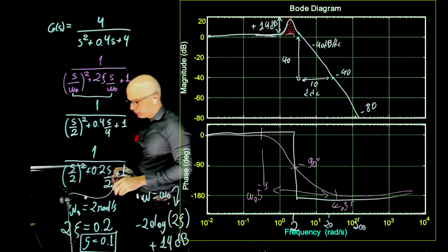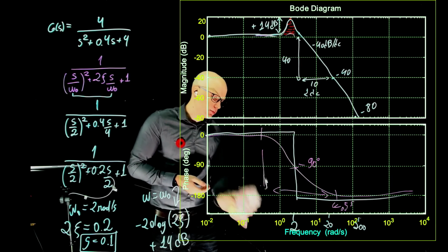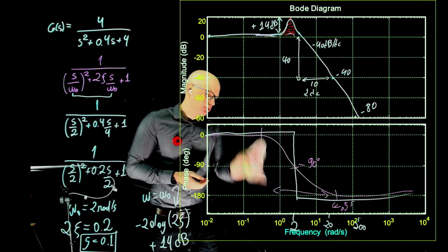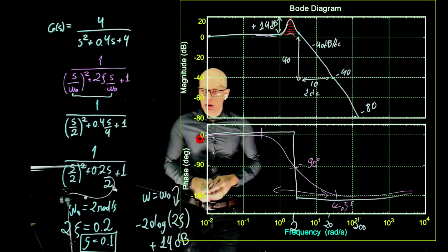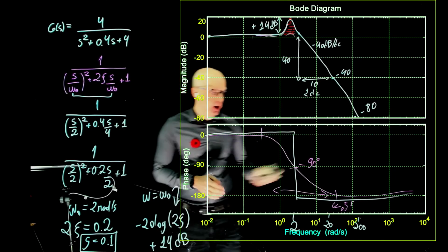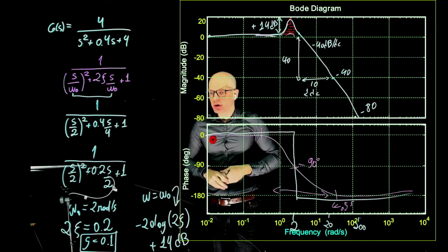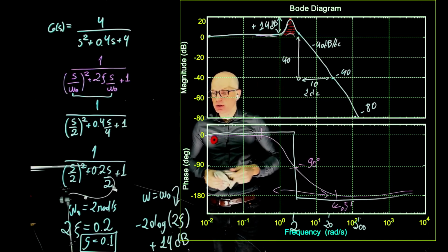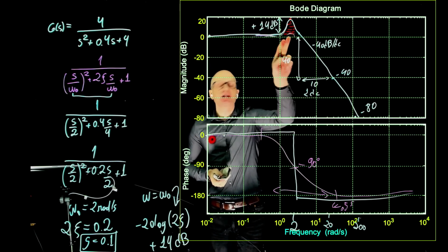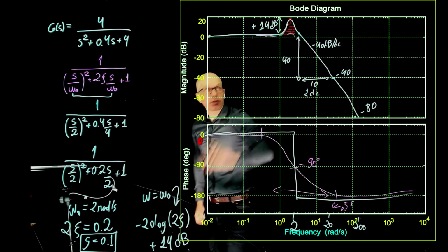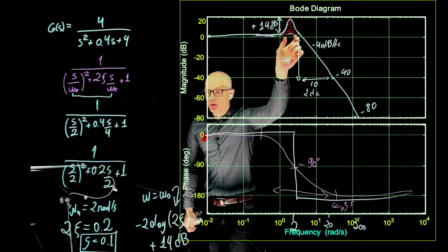So how do we figure out for assignment questions and exam questions how wide that bump is? At what point do we start moving into the negative 40 dB per decade slope? I don't know how to do that. It's really something that we need to use MATLAB for. I would say a good indication is if this 14 dB is a lot, this needs to be relatively sharp.